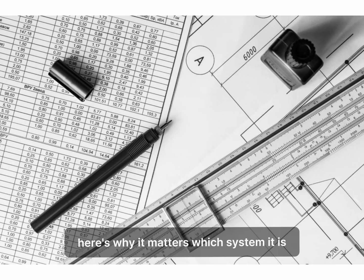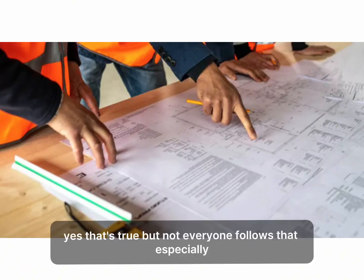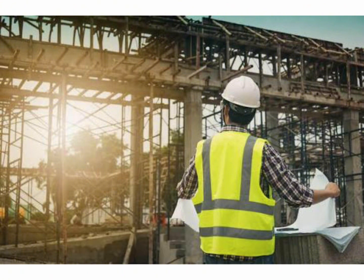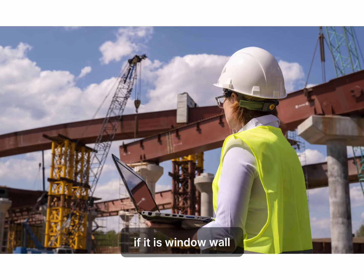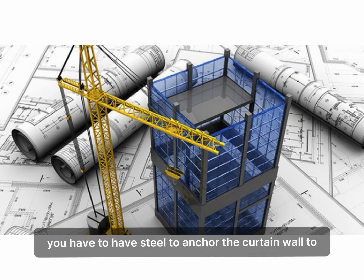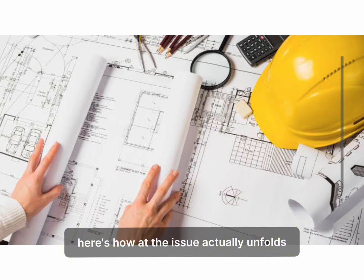Here's why it matters which system it is. Some of you might say, well, the specifications trump the drawings. Yes, that's true, but not everyone follows that, especially whoever is doing the structural components of the buildings. Each system is anchored differently. Structural components must be designed to fit each system. If it is window wall, you have to design the concrete slab to carry the load. If it is curtain wall, you have to have steel to anchor the curtain wall to. Each system works differently.